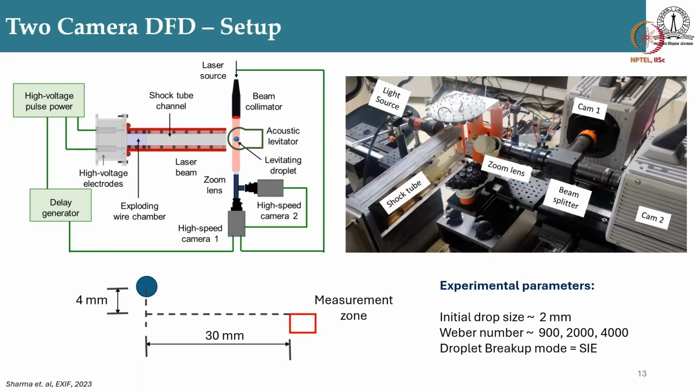And to do that experimentally, how do we place two imaging sensor planes with a fixed or predetermined offset? That is done using a splitter plate. So we have this backlight imaging system. So this is the light source. It comes like this through the measurement volume and comes over the lens. After the lens, we place a splitter plate that divides that light beam into two parts, and we can now take and place the cameras in both of these paths. And by changing the position of the camera, we change the path length, or we change the value of S.